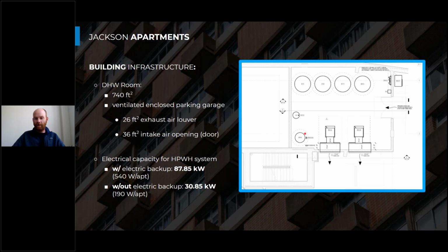And so we have an electric water heater that has a high capacity to it. And we also did include electric resistance elements in the temperature maintenance storage tank. So essentially that's another water heater, but we kept those element set points lower than the heat pump set point, so that the heat pump is always running first, and hopefully those electric resistance elements aren't coming on.